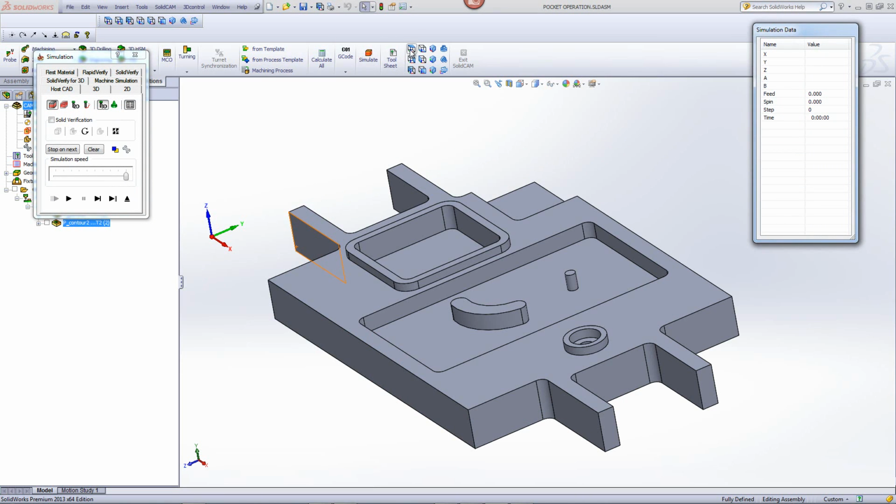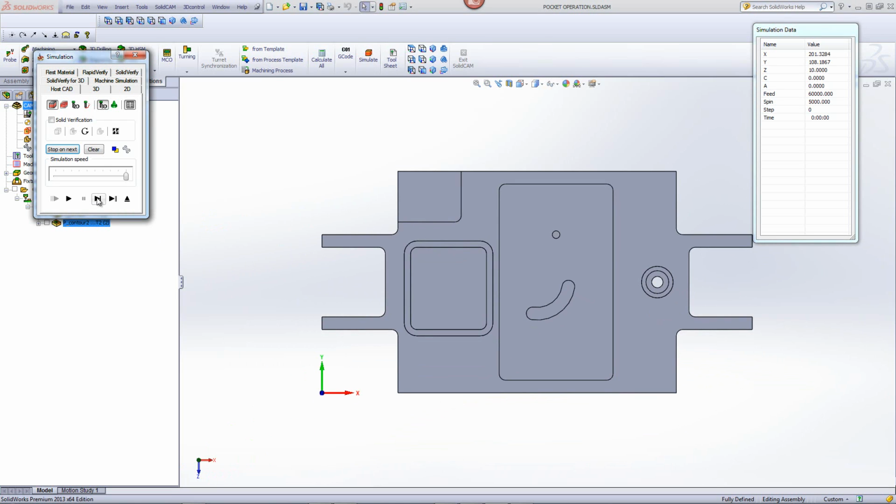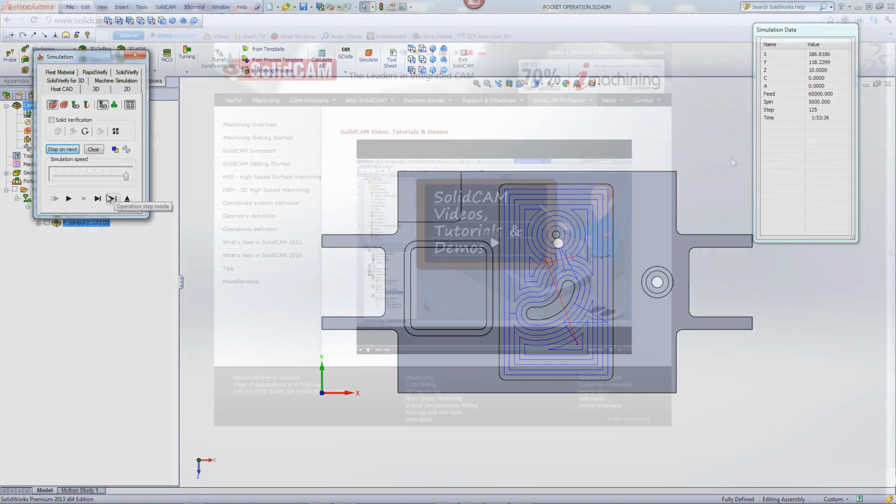If we were to take a look now at our toolpath, the toolpath again works around the area itself over there. And what actually happens is when it gets to its finished cut, it gets closer to the islands itself. But now you'll note that it connects them together. It'll start its finished pass now, go around, go to one island, and then go to the next island.